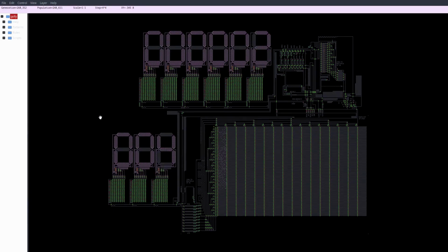256 generations of the automaton are simulated each frame at 60 frames per second, and each instruction takes 2,880 generations to execute, so the processor is currently running at about 5 Hz. Let's increase the speed to around 85 Hz. It will stop after reaching the largest Fibonacci number that can fit within 2 bytes, which is around 46,000.